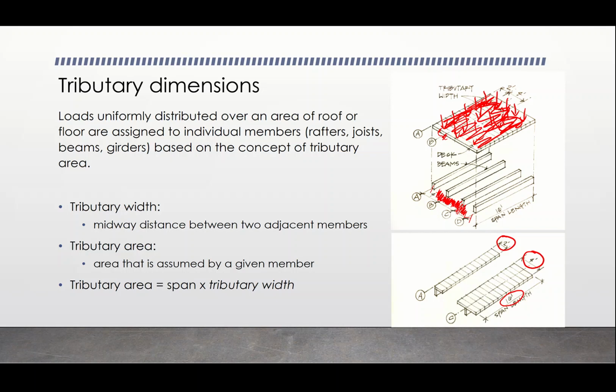Okay, so what we should be able to see is, it's 3-dimensional, this is like our first 3-dimensional look, but what we're always trying to do is get back into 2D, get it back onto an X and Y plane. So how are we going to squish this loading to being flat again over these beams? That is overall the concept of load tracing.